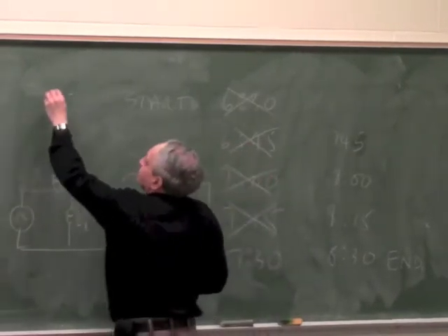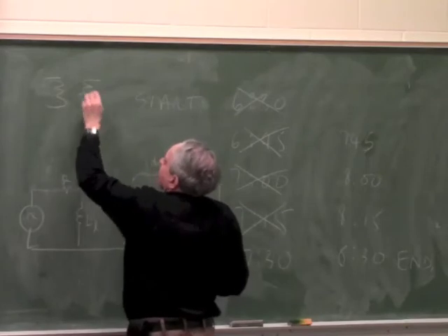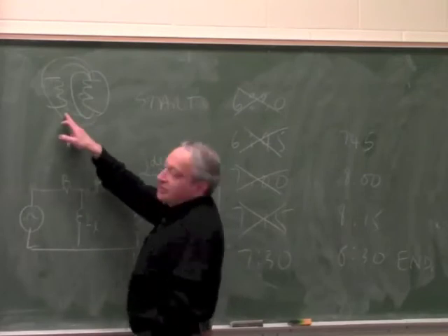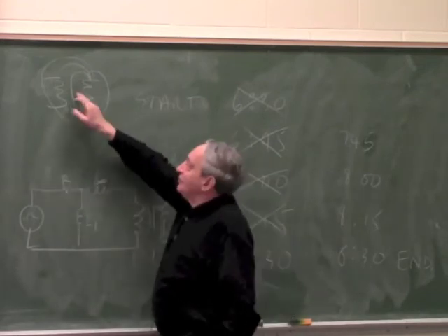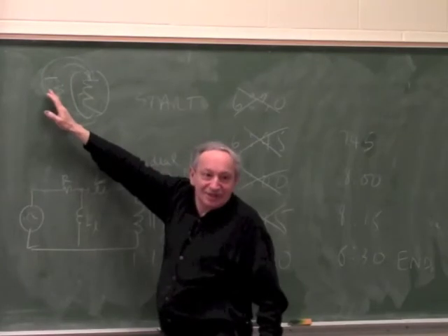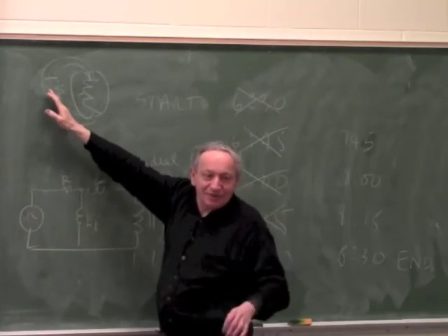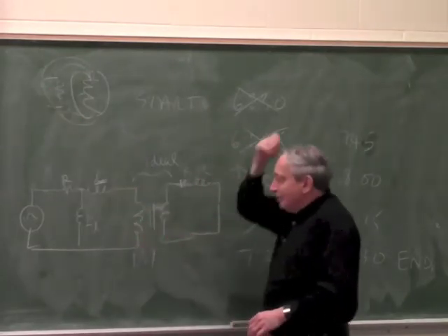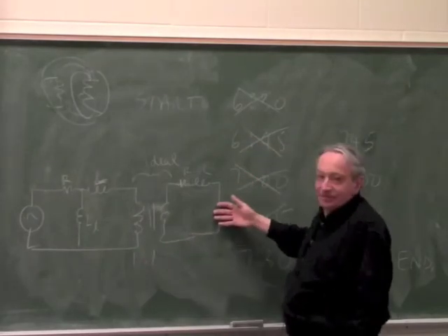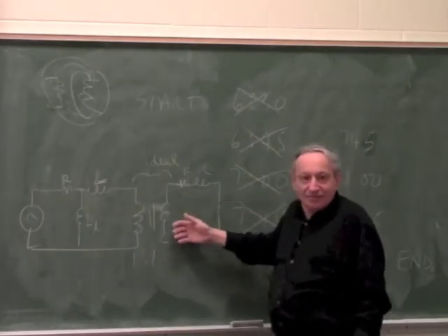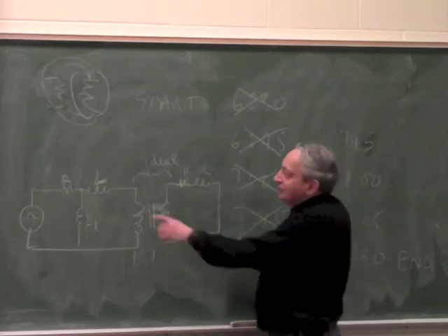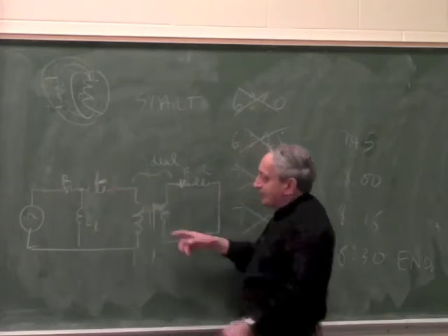So if you have physically a transformer and you have two coils, you want all this flux to engage the other coil, but some flux goes without engaging the other coil. So this part of the flux just looks like an inductor. The flux which couples both doesn't have inductance. I know I'm going very fast, but when you take a transformer like this, at zero frequency there is zero current here, because there is no change of flux. But at a very high frequency there is also zero current here, because this inductor will limit the current.